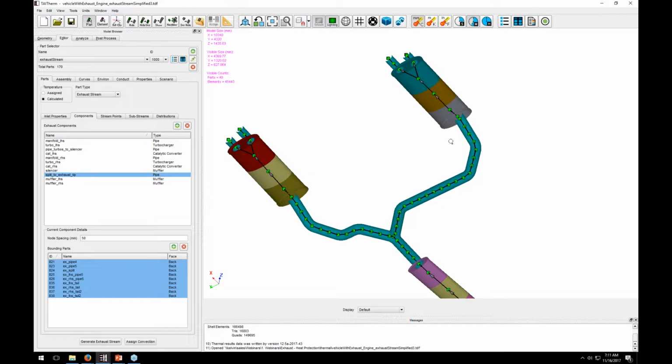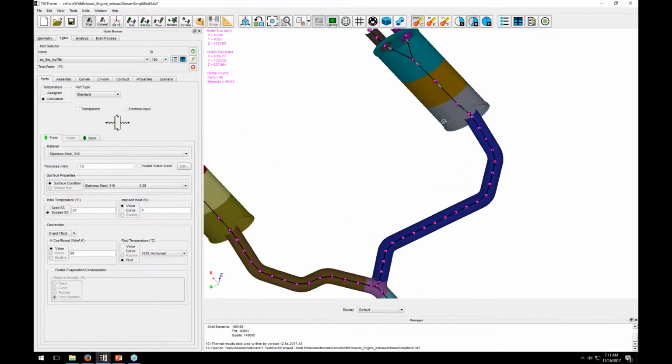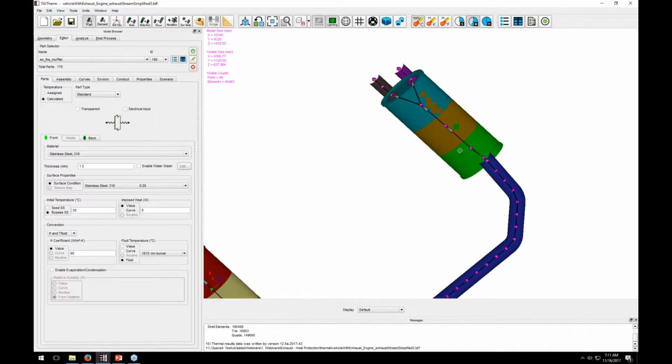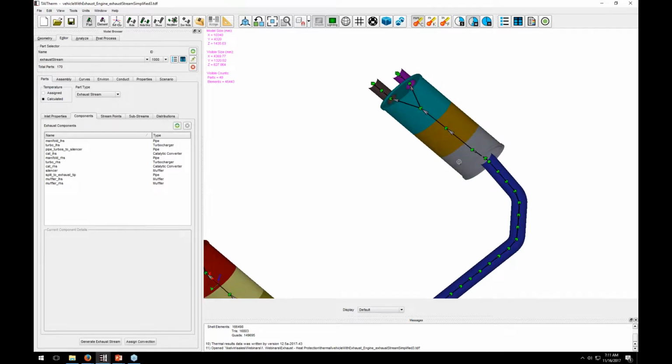other components in your setup until you want to specify maybe your muffler right here. So here is, again, similar to how we set up the silencer, the muffler. And this, again, includes 3 chambers. I think another thing to note here is that for each chamber that you have, you will get 1 node at each of these. So it's important to know if you have an intricate muffler or something you want to set up, you'll want to make sure to break that up accordingly.